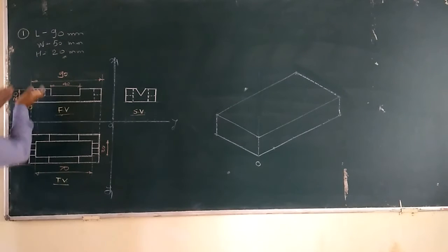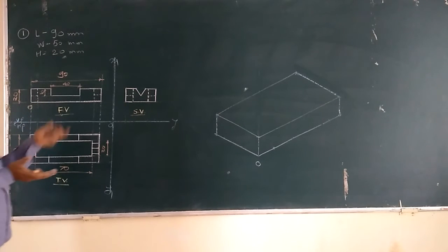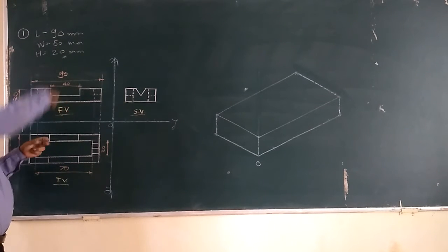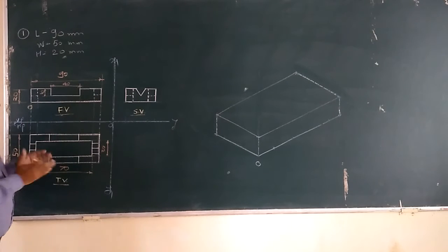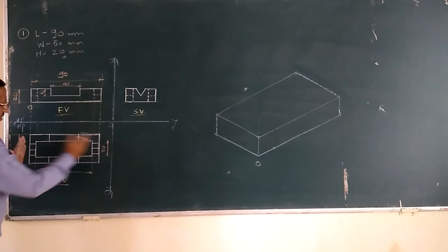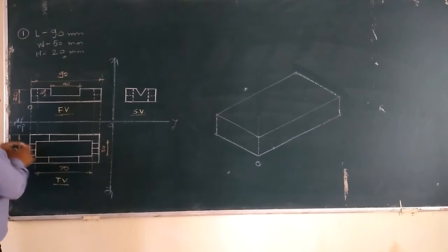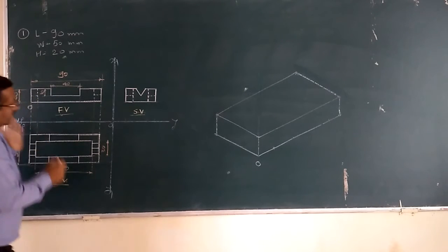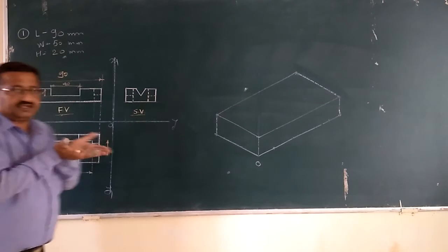Such a V-shaped notch will be cut. Here, such a rectangular part is cut. It has been cut in these two walls. But in these two left and right walls, in top view, three lines are emerging, while in front view, only a single dotted line. Inside it is clear that it is a V notch.